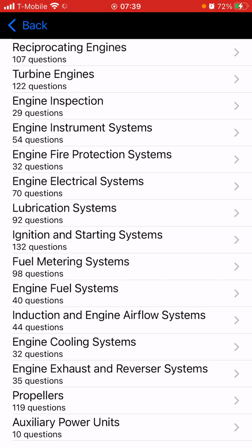Oil picks up the most heat from which of the following turbine engine components? Turbine bearing. In the turbojet engine, the oil picks up most of the heat from the turbine bearing. The recommended aircraft engine lubricants are mineral and synthetic base. The most satisfactory lubricants for aircraft engines have either a mineral base or a synthetic base.